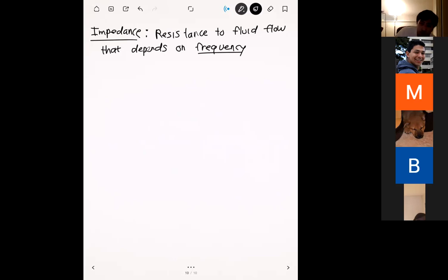And this is important because the whole concept of viscous resistance is fine. Remember that for viscous resistance we had our modified Ohm's law, so delta P was equal to Q times R. We had a linear relationship here, and this is fine for just a resistance, and fine if you have a rigid tube. But in general, it doesn't quite follow this relationship in the cardiovascular system.